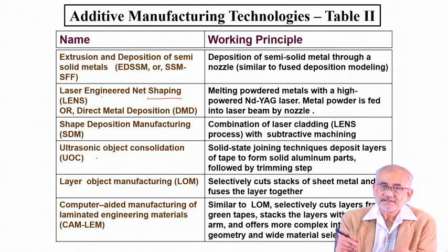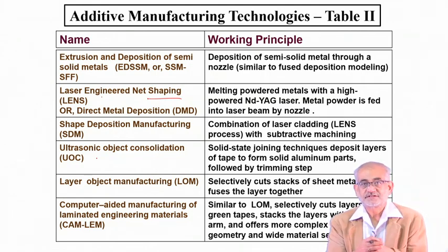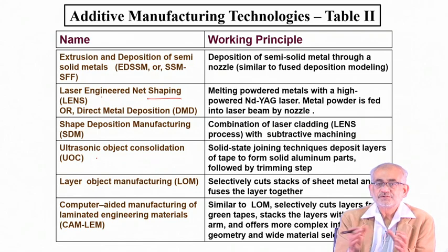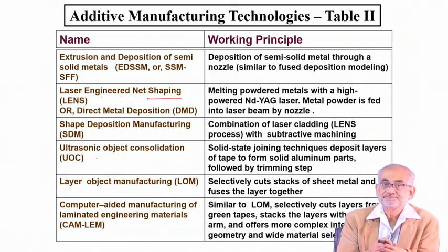And by controlling the laser and its power, you actually can make it melt, you can make it clad or deposit, and make it a very firm and dense structure. You can even create a lot of gradation in terms of thickness, in terms of shape, in terms of porosity or other physical or chemical parameters. So the possibility is literally infinite. You actually can do complete engineering of finished component development, manufacturing, using a single tool of laser with a powder feeder or a wire feed or some other material feeding system.